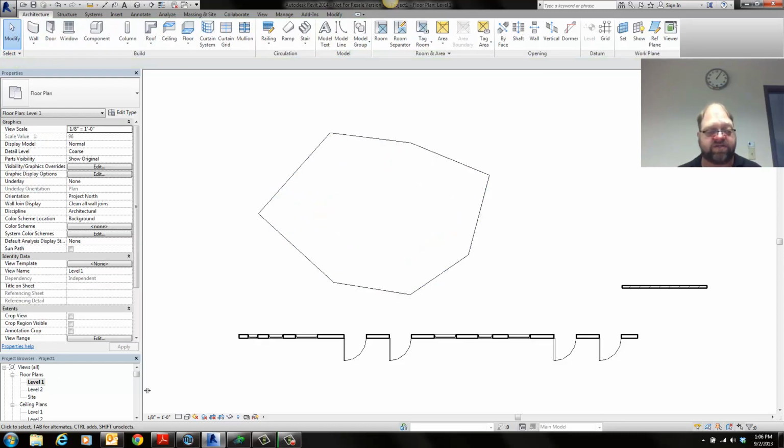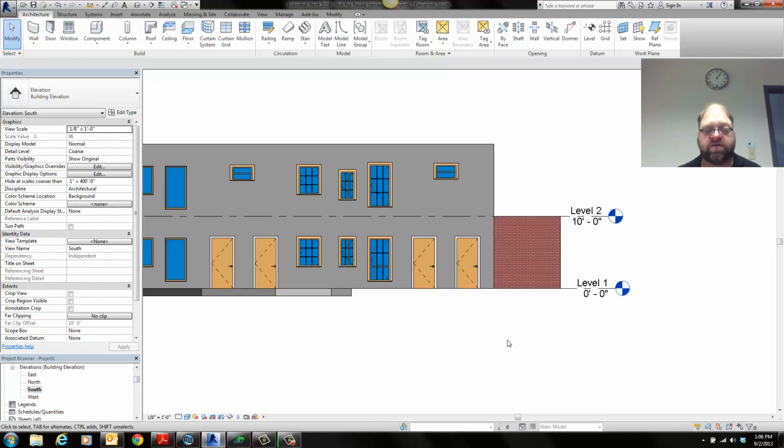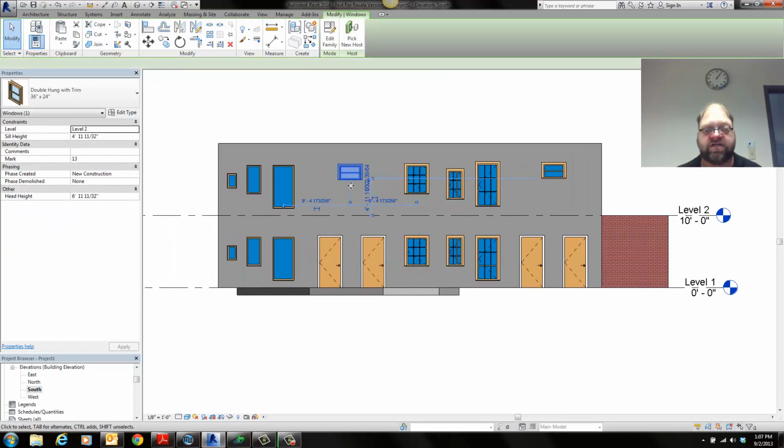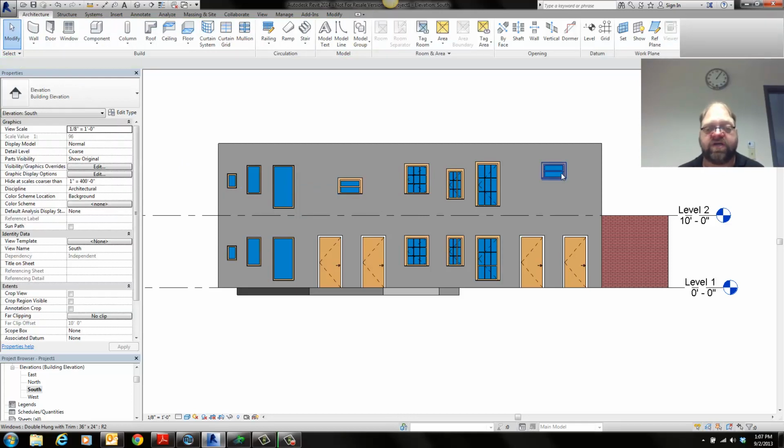Or we have the instance properties on things. So if we need to change individual items, we can change an individual item by resetting its sill height or whatever to be 3 feet, and move it where it needs to be. It doesn't affect this one over here. So that's another way to control, is instance properties. Now, whether it's an instance or type property depends on how the author wants to define that. And then all of these parameters, of course, have different kinds of relationships, whether they're implied or direct or